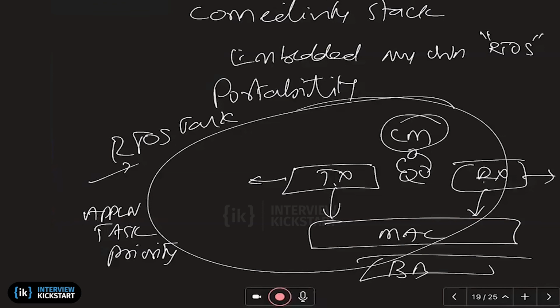So basically, what does the bare metal give? The events have to be fed, right? Event pump or message pump. Now, as long as your RTOS can give me that, I'm done. I need not get it directly from the ISR or from the hardware, right? It can come through the OS mechanisms. So all I need is an event message pump.